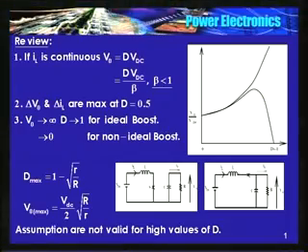In this circuit, when the switch is closed, the capacitor is supplying power. If most of the time the switch is closed, the capacitor continues to supply power to the load, so it will discharge. I can't assume that this voltage will remain constant. Eventually it will become 0 when d is equal to 1. Of course, you cannot achieve that condition because something else will happen here.